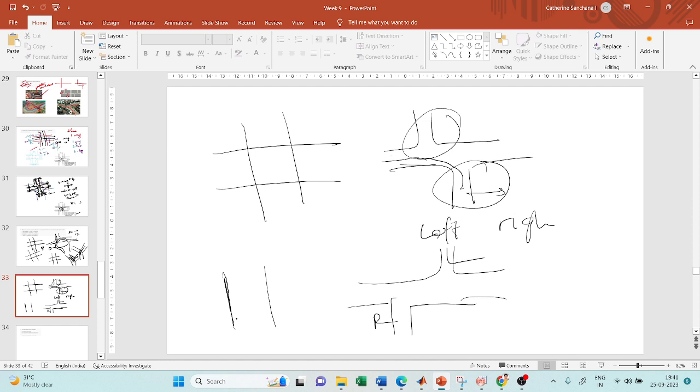If you are traveling in this lane and you have to make a right turn, providing a separate provision means they will provide a separate lane at the end of this intersection exclusively for right turning vehicles. So this is providing an exclusive lane, a separate provision for left and right turning traffic. So this will also reduce the conflict points.